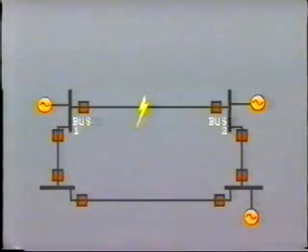Incidentally, in order to obtain high-speed reclosing, it is essential that the temporary fault is cleared by high-speed simultaneous tripping at both ends of the line. This means pilot protection must be used. In this case, high-speed reclosing will be virtually simultaneous at both ends. But remember, if it's necessary to take the pilot protection out of service, it's also necessary to block the high-speed reclosing action.